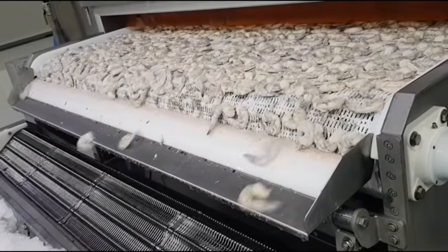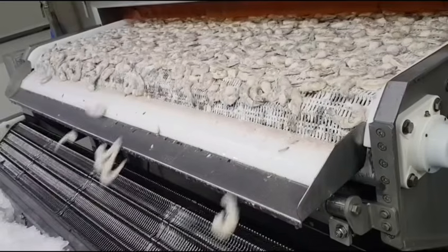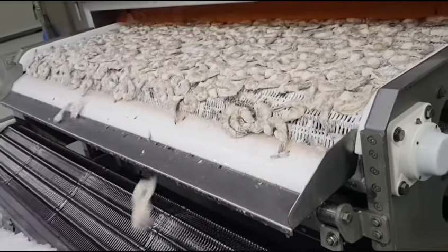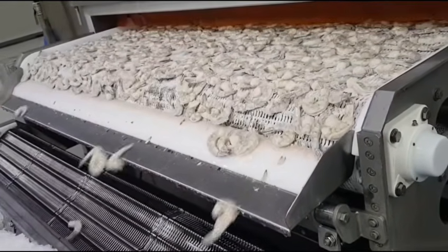We are freezing the product at minus 40 degrees centigrade, which attains the core temperature of minus 20 or minus 19, 21, like that. Minus 18 degrees centigrade core temperature and minus 40 degrees centigrade freezing temperature. As per the validation study, we can hold the product in a cold storage for 24 months. But unfortunately, the shelf life of the product is reduced to 1 year.